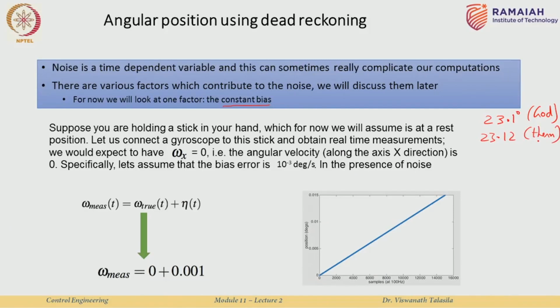Let us go to a different room where the temperature is 43 degrees, and your thermometer will show 43.02. Go to another place, and there will always be an offset from the actual true temperature, in our particular example by 0.02 degrees Celsius. This constant offset is called a bias, and it is there in every sensor.